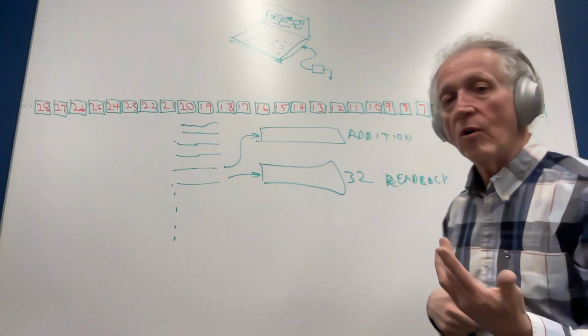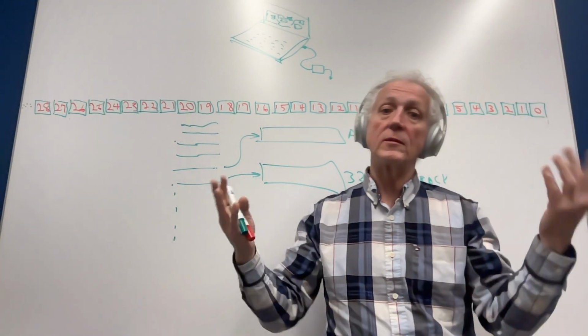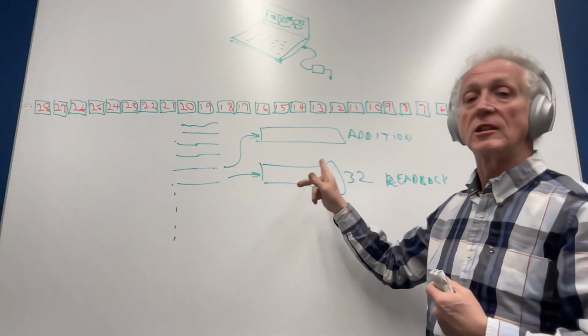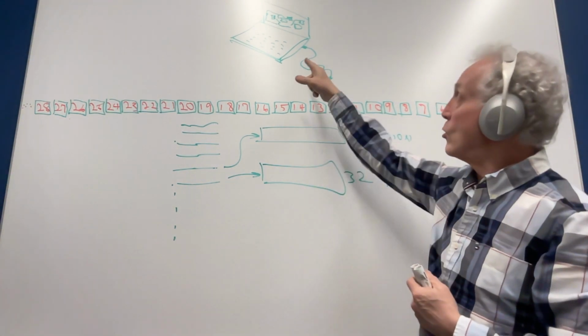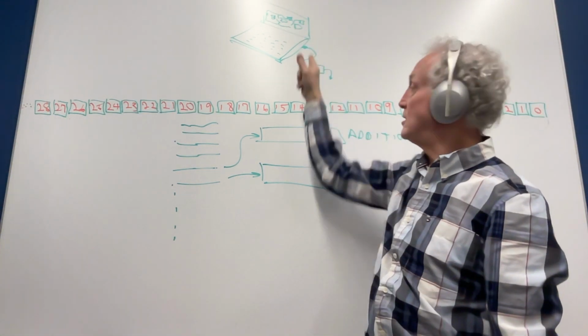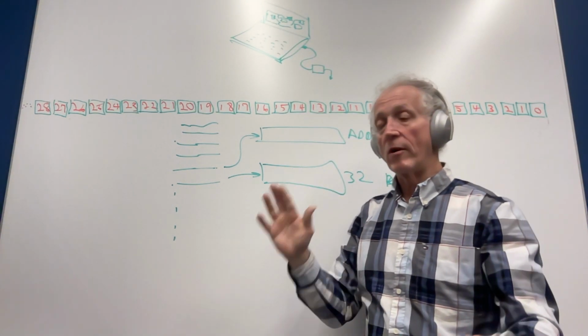So that's how it works in a Sigma 300 core and a Sigma 200 core, except the latter is only 28 bits. There will be a memory location that gets updated, and all the readback function in Sigma Studio does is read that memory location and bring it up. That's how that works.